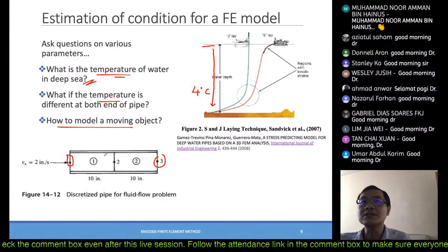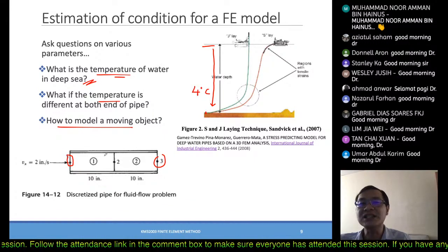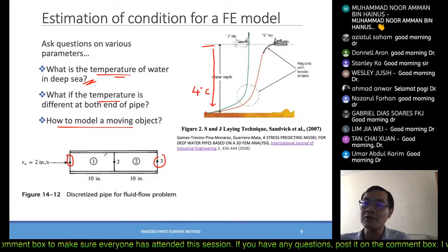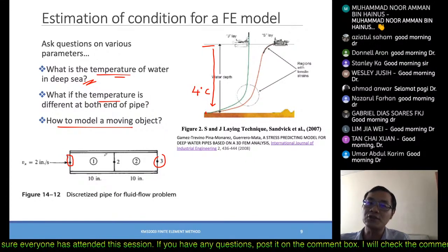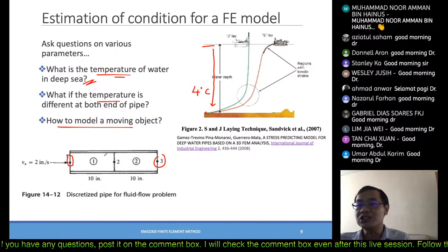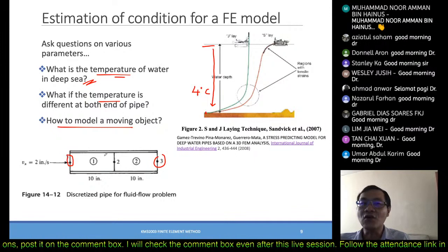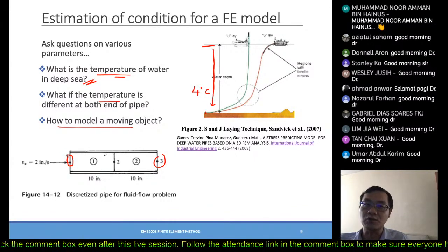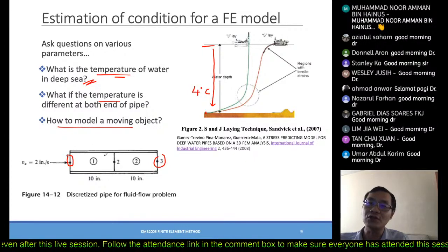Previously we talked about when the temperature differences are very high, when the temperatures go up to maybe melting point from room temperature, then in between there is a phase change and other things. Therefore, in that case we would want to use the temperature dependent material property. Similar for the fluid itself.